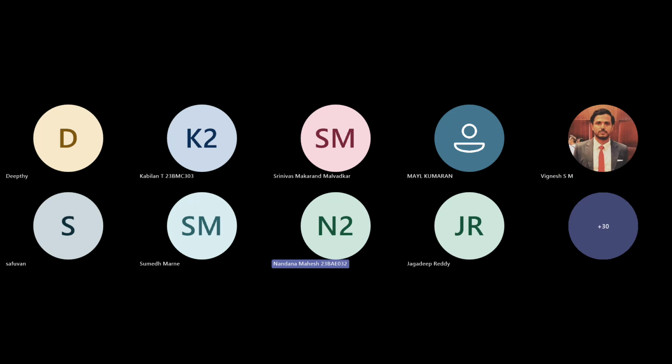Sir, from the solution, can we also get the total thrust generated by the multirotor? Yes, ma'am. So yes, that is possible. Even each and every particular propeller is also possible to get, and also the complete body. You have to select the unmanned aerial vehicle, that complete body, give the right axis and just generate, click force. It will give you the force. If it's an aerodynamic thrust, yes, it's possible.